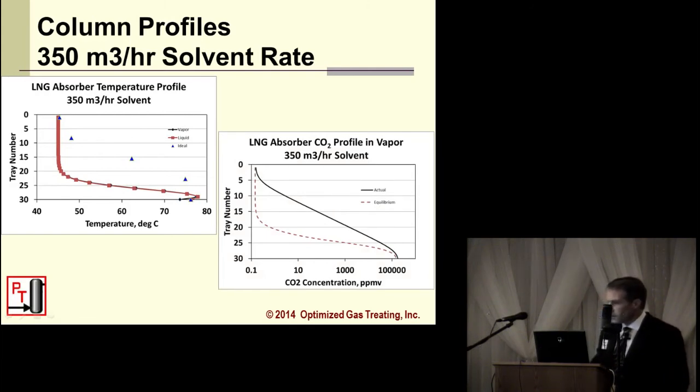In terms of the CO2 concentration, as we go up the column, we're removing CO2. I've plotted the equilibrium values above the solvent that the rate model is computed. That's this dashed red line here versus the actual CO2 outlet here. And you can almost come into this drawing and step off 1, 2, 3, by the old McCabe-Thiele method, 4. There's my 5 stages.